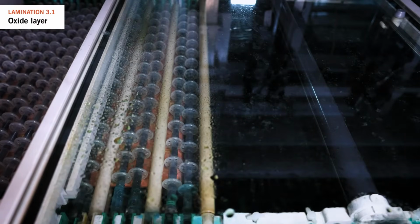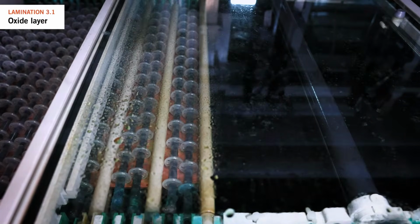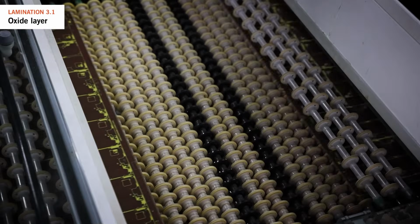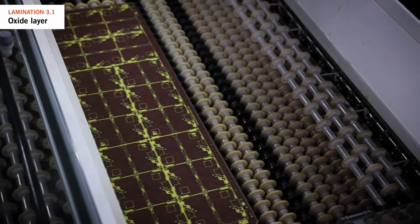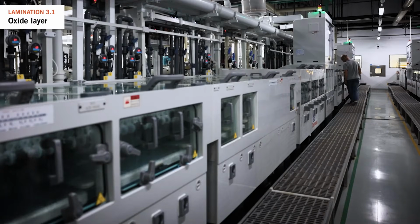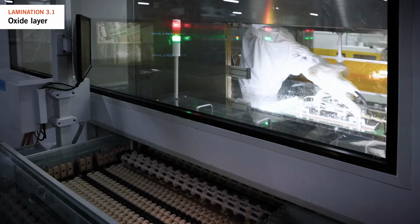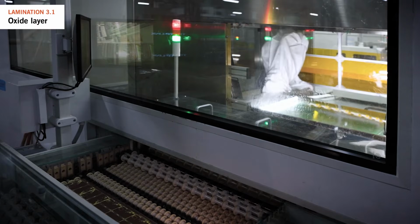While it may seem straightforward, it's crucial to carefully manage the chemistry and handle the treated cores with care. The thin oxide layer is very sensitive to damage, and any damage could risk a failed bond during lamination, potentially leading to delamination of the bonded multilayer.